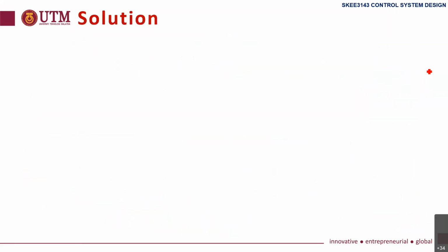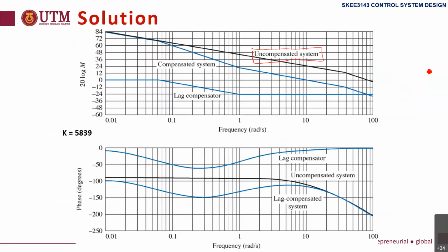Perhaps this one is clearer. If you check the uncompensated, this is 0 dB, you make a line here. Here is Kv, 162.2. Of course, you will not get exactly 162, because of the accuracy. The 0.2, of course, you cannot get.